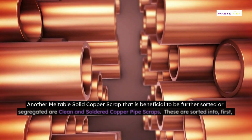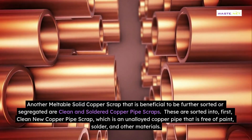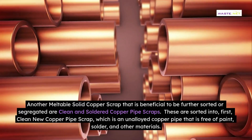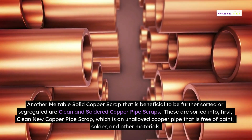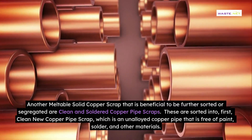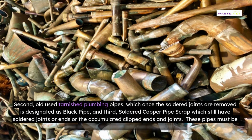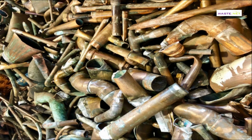Another meltable solid copper scrap that is beneficial to be further sorted or segregated are clean and soldered copper pipe scraps. These are sorted into: first, clean new copper pipe scrap, which is an unalloyed copper pipe that is free of paint, solder, and other materials. Second, old used tarnished plumbing pipes, which once the soldered joints are removed is designated as black pipe. And third, soldered copper pipe scrap which still have soldered joints or ends or the accumulated clipped ends and joints. These pipes must be free of brass or bronze and non-copper fittings.